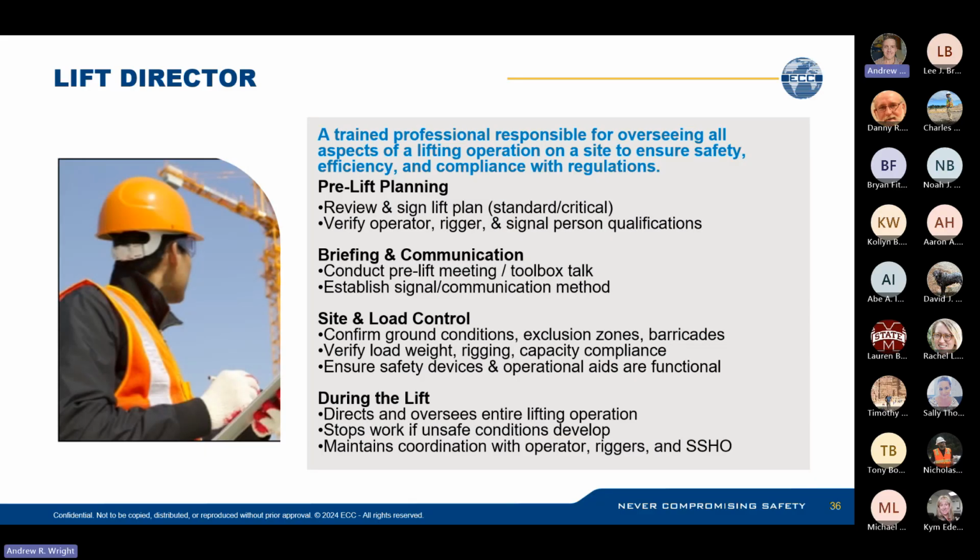During the lift, they're going to direct and oversee the entire operation. They're going to stop the work if unsafe conditions develop, and they're going to coordinate with the operator, riggers, and SSHO. And in certain conditions, you could have the operator also be the lift director. It kind of depends on what you're doing.